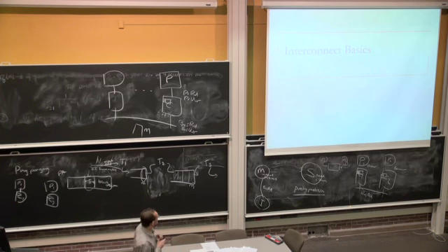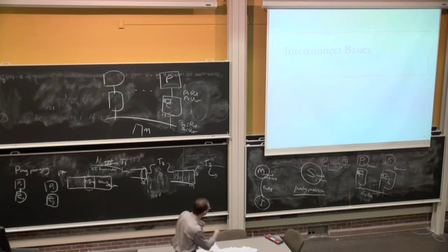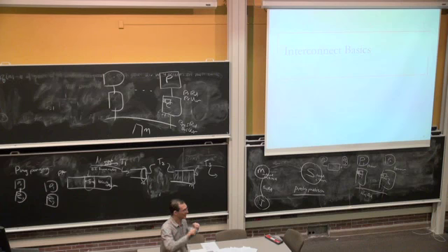In fact, that brings up a good point also. You could have the same MESI protocol, exactly the same states, if you will. Maybe you don't keep track of the states exactly the same way you would do. But that could be implemented as part of a Snoopy cache or as part of a directory, right? It's just the operations that need to be performed would be different, right?